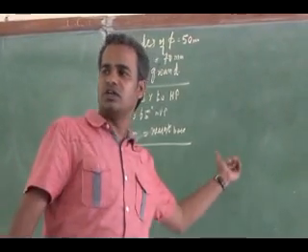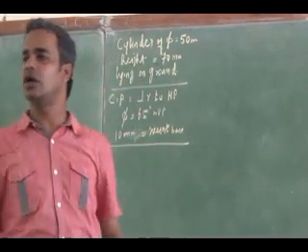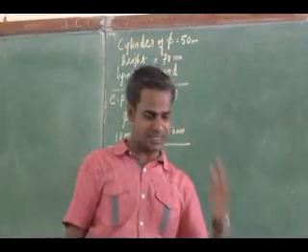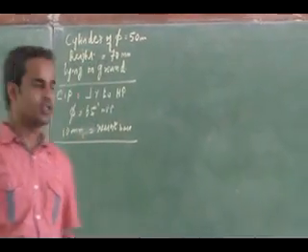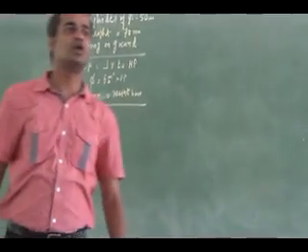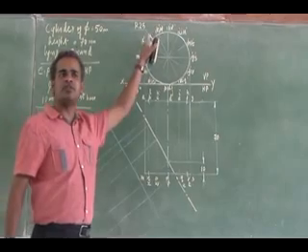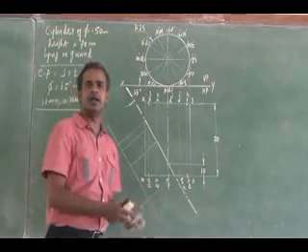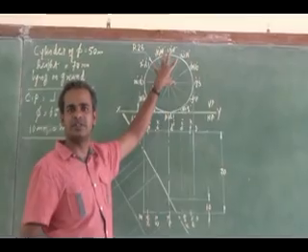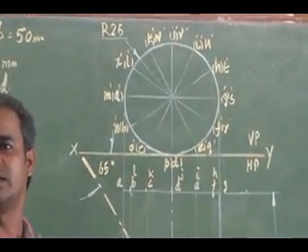Okay, top view, sectional front view, and since the plane is inclined, you should get a separate true shape of section. So draw the top view, sectional front view, and true shape of section. You have drawn the front view and top view, right? You notate the two bases in letters, right? Why? Because the cutting points will be notated in numbers.